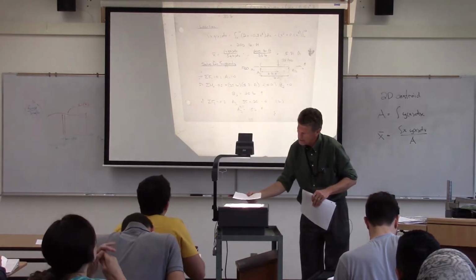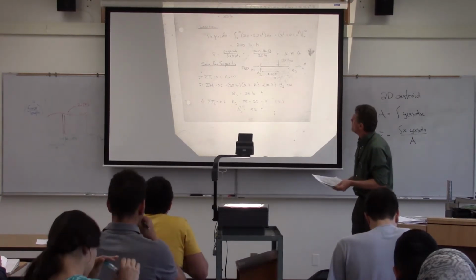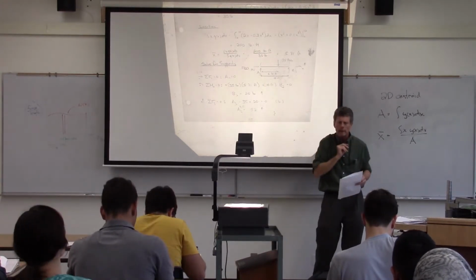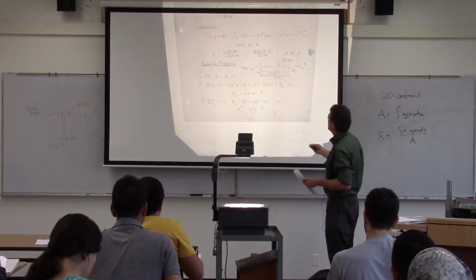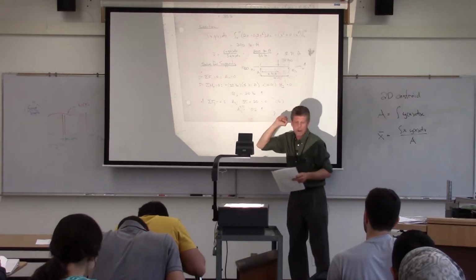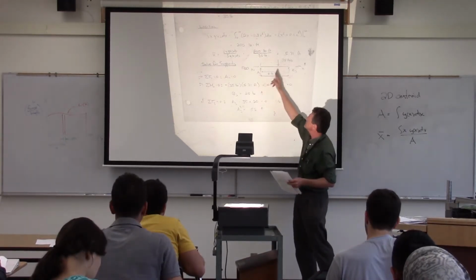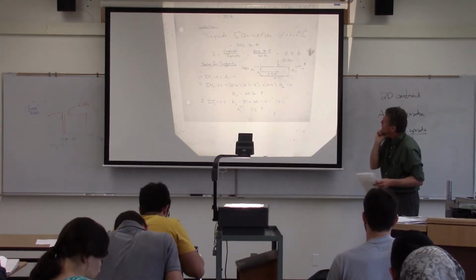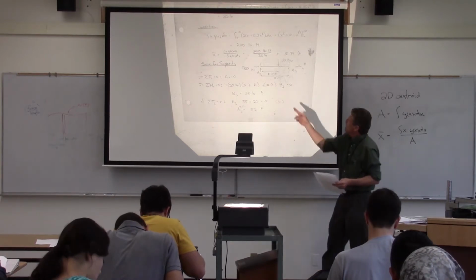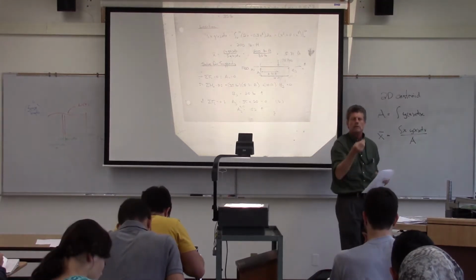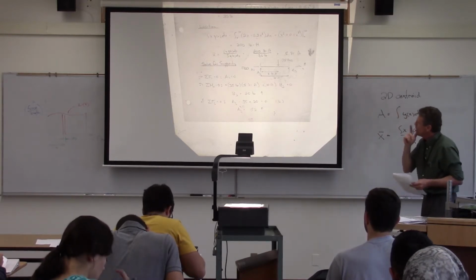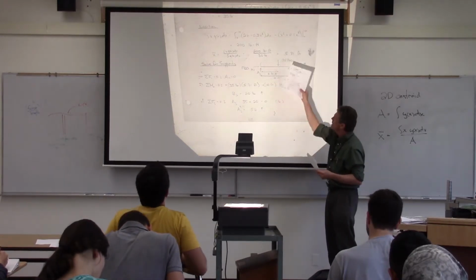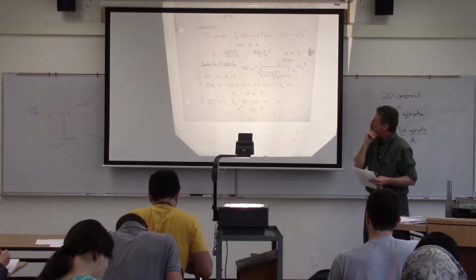Again, I think you've got most of the rest of it here. What we're then doing is going back and creating our free body diagram. We're going to substitute in A_x and A_y, the two components of the force at A, and the one force at B_y. And then the thing that I need is that known load. What is its magnitude and where is it acting? I've now been able to establish that by finding the area and the centroid of that area, and I've now located that.